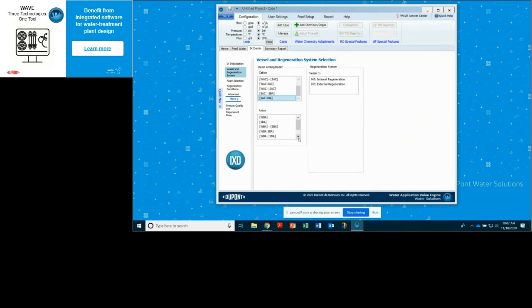Just one question that came in that would be relevant as we're going is, what is a BV? Donna, if you just want to give a quick explanation. Oh, sure. A bed volume is a reference to the volume of resin that's in your vessel. However many cubic meters are in the vessel, that is the bed volume. Right. So a space velocity of 20 BVs an hour would be, if you have a 1 cubic meter vessel of resin, you would be flowing water at 20 cubic meters an hour. So it's volume of water divided by volume of resin.